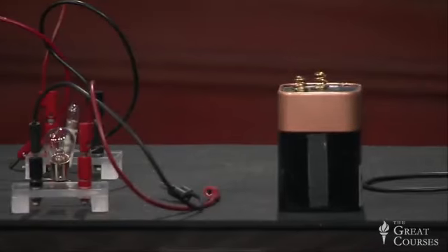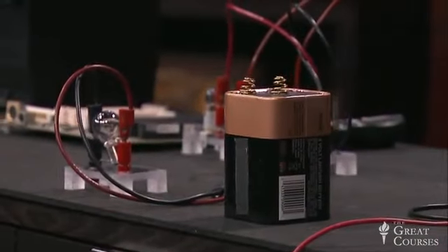And so now I'd like to try to characterize an ideal battery by drawing a graph that shows how the voltage and current are related in an ideal battery. And as I do that, remember, an ideal battery maintains the same voltage across its terminals, regardless of how much current you or the external circuit it might be connected to is asking it to supply. For example, that 6-volt battery I just showed you is sitting on the table with nothing connected to it. It's not being asked to supply any current right now. It's supplying 0 current. But even if it were supplying 100 amperes of current, if it were ideal, it would still have 6 volts across those two terminals.